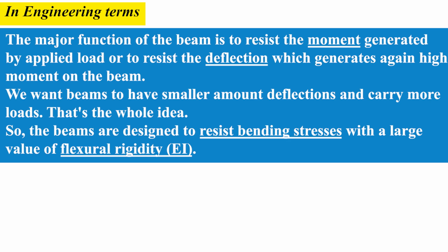The major function of the beam is to resist the moment generated by applied load or to resist the deflection which generates again high moment on the beam. We want beams to have smaller amount of deflection and carry more loads. That's the whole idea. So, the beams are designed to resist bending stresses with a large value of flexural rigidity, EI.